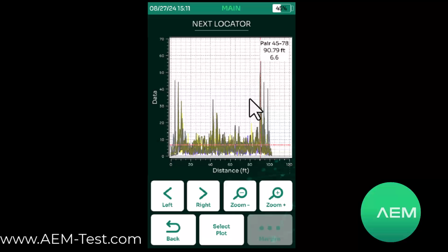One of the most common cable failures for copper cable. We can see here a TDR trace of the cable. Along the bottom here you see the length, and then here we see the magnitude of the event. And we see these event markers, and we can see the first one starts at about 3 feet or so. It's actually going to cover the beginning where we're connected to the panel at the main end.